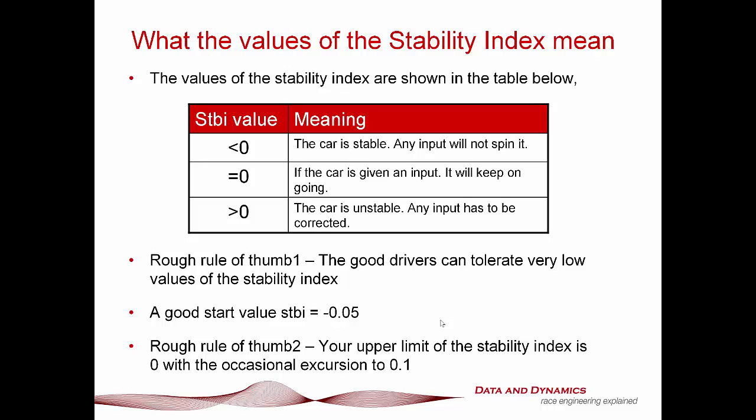Ultimately, that has had its evolution in the extreme agility designs, such as the Sukhoi Su-35S Flanker, the forthcoming Sukhoi T-50 PAK FA, which has now got the designation Su-57, and to an extent the Chinese Chengdu J-20, where in addition to being pitch unstable, they've also got relaxed static lateral stability as well.